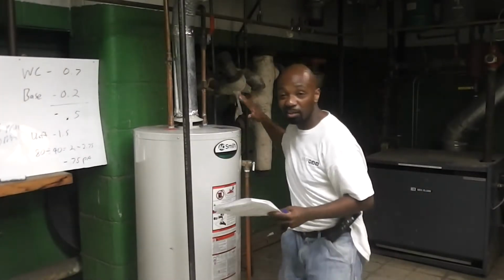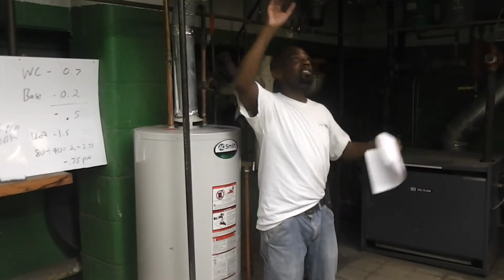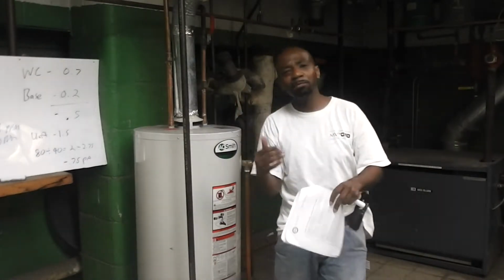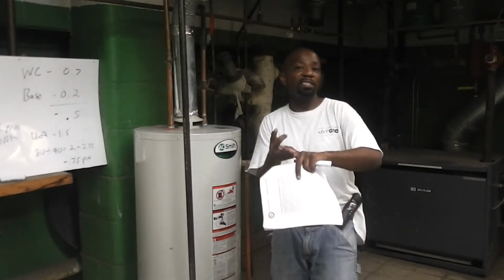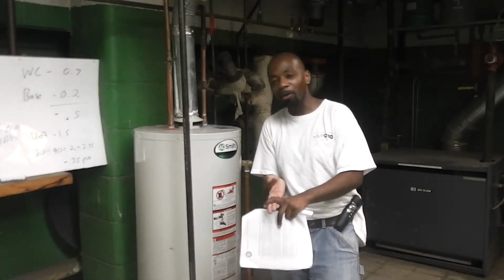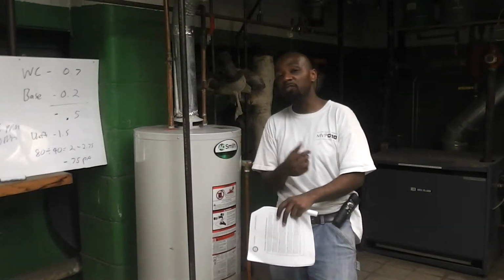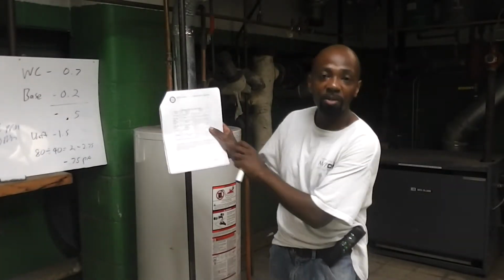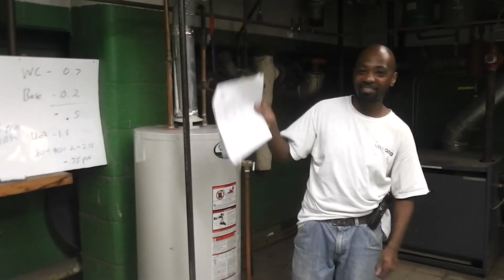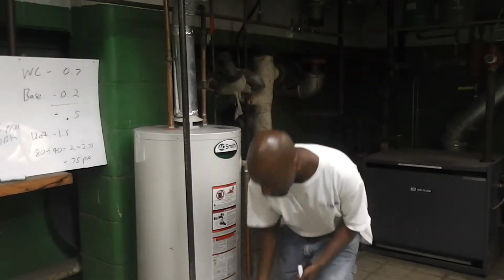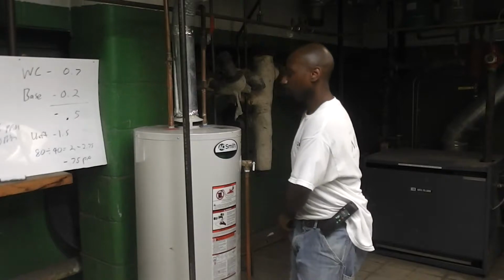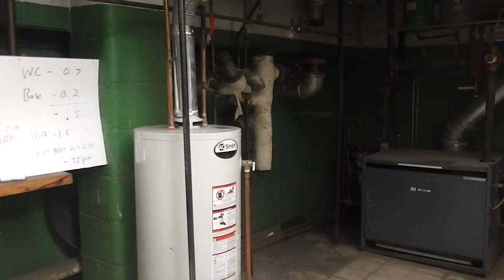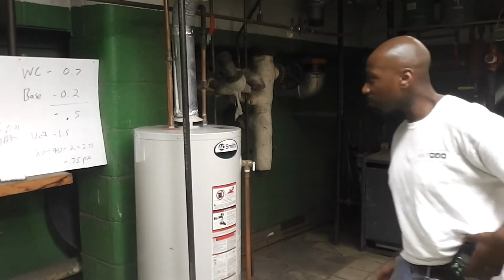So keep in mind, this is not the only combustion appliance. This is actually tied into another combustion appliance. It's actually coming vented with a boiler. So I'm going to run those same tests, the spillage, the draft, as well as the CO, the undiluted CO, on the boiler as well. While this thing is running, I want to see if I get good readings. And of course, depending on readings I get, I'm going to refer to my combustion safety action level charts. Let's move on to the boiler. This thing's already running. Let's do spillage. Where's the smoke still?